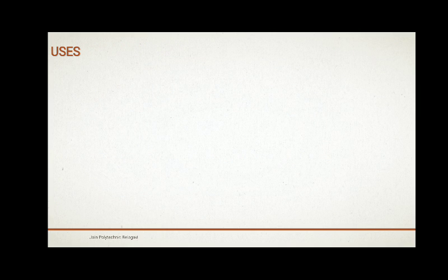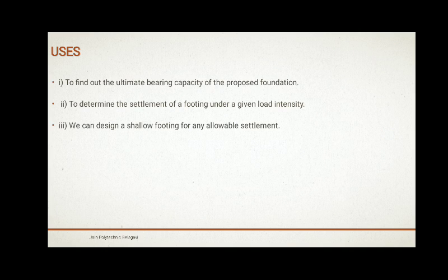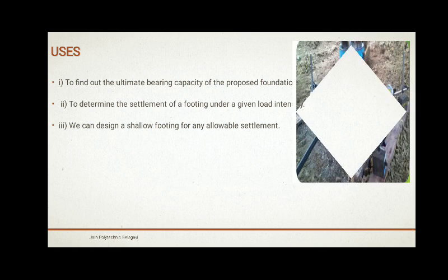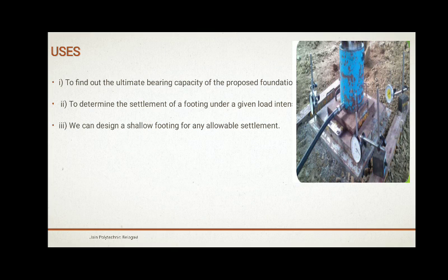What are the uses after conducting the plate load test to determine the ultimate bearing capacity? The uses are to find out the ultimate bearing capacity of the proposed foundation, and to determine the settlement of the footing under load intensity. We can design shallow footings for any allowable settlement. This is the apparatus of the plate load test method by gravity loading.